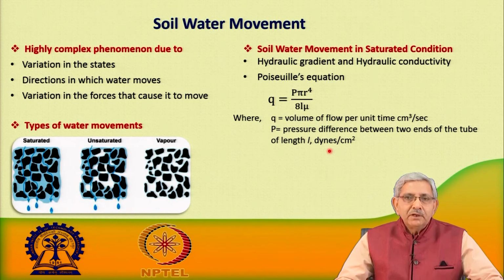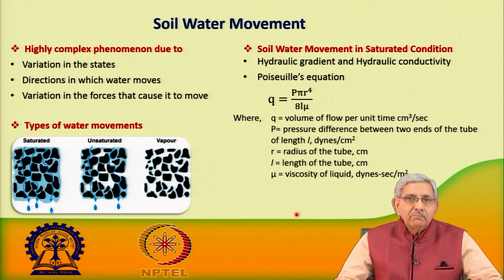So, it forms a capillary action, and the important part is the diameter of this capillary tube when the water flow takes place from the soil. You can see how the diameter plays a role: it is the fourth power of the diameter which is dominating the rate of flow. It is inversely related to the length of flow or length of capillary tube, and inversely proportional to the dynamic viscosity of the fluid or water.